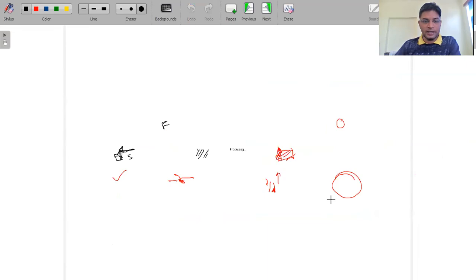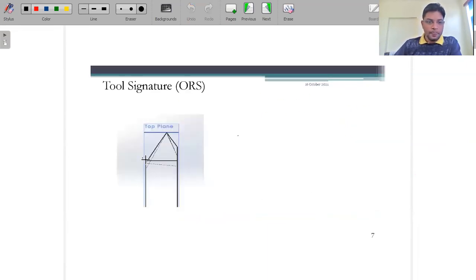Now why are we calling it the approach angle? There is one more figure. Initially we kept this as a longitudinal plane, and if we are talking about the auxiliary plane, then we have tilted this plane in this direction. So this is now the auxiliary plane. The angle from the inside, we call this lambda, the principal cutting edge angle. Initially CS we were measuring from the longitudinal plane to the cutting edge, but lambda we are measuring from the inside, from the horizontal. So this is lambda.